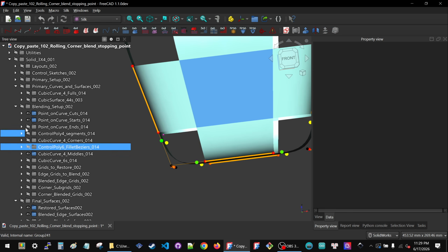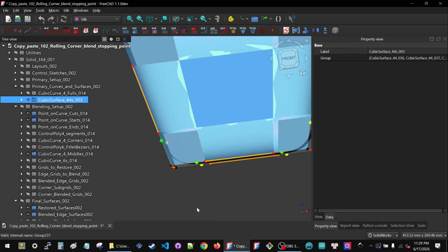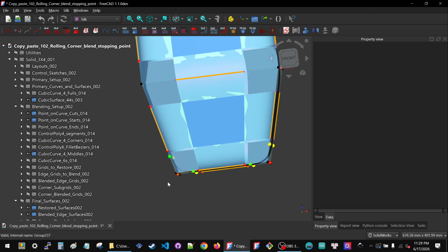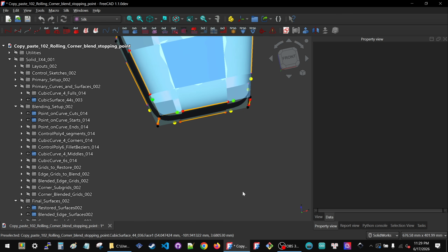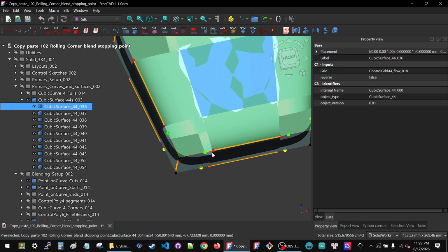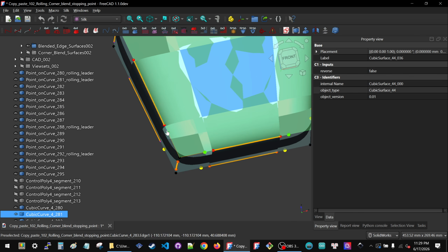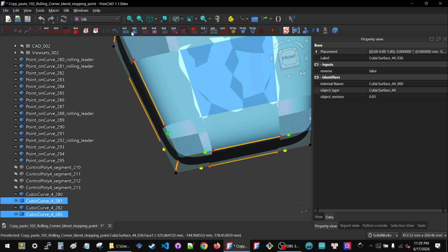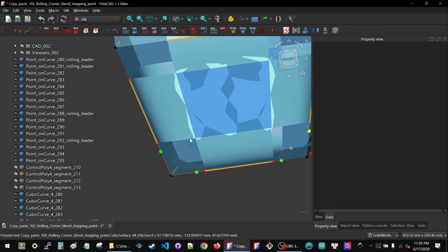So let's do it. I'll need the overall surfaces because that is what I make the segments from. So I select this surface, I select this little curve right here, this little curve right here, segment, and there you go. This little piece is what will become the rounded triangle. But right away, let's also make the new piece along the edge that will correspond to the new blend.